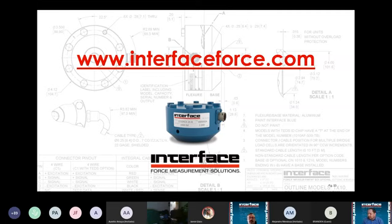So cables: do the cables and amplifiers affect the results of load cell calibration? I think that's something you can respond to, Keith. I think there's a lot that goes in there, and there's different ways of doing it. So touch back maybe on in situ and system level cal. Yeah, I would say the answer to that is absolutely they can. They don't necessarily, but they absolutely can have a large impact.